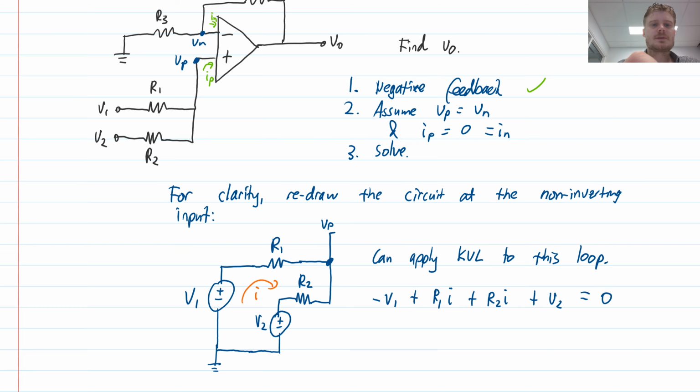And this is why it was important to pay attention, because you notice I actually end up with different signs here for my two different voltages. As I proceed all the way around that loop, those are the signs that I encounter as I approach those voltage sources. So this is why this one was a tiny little bit tricky.